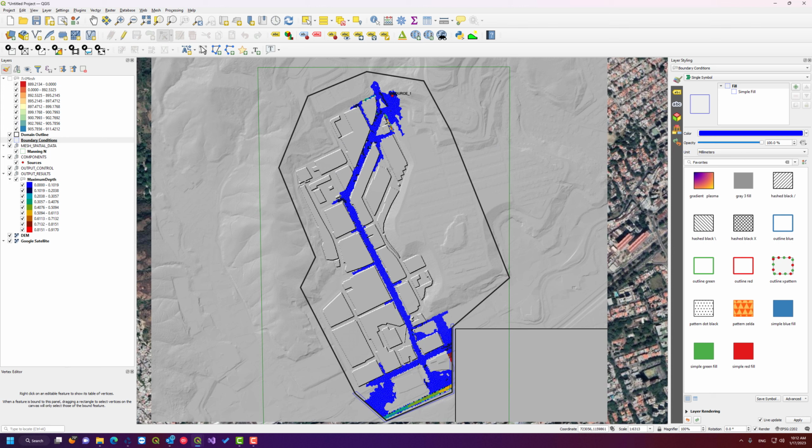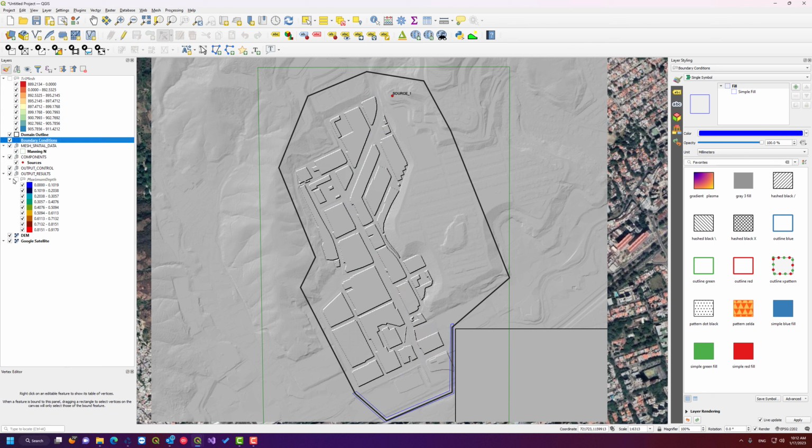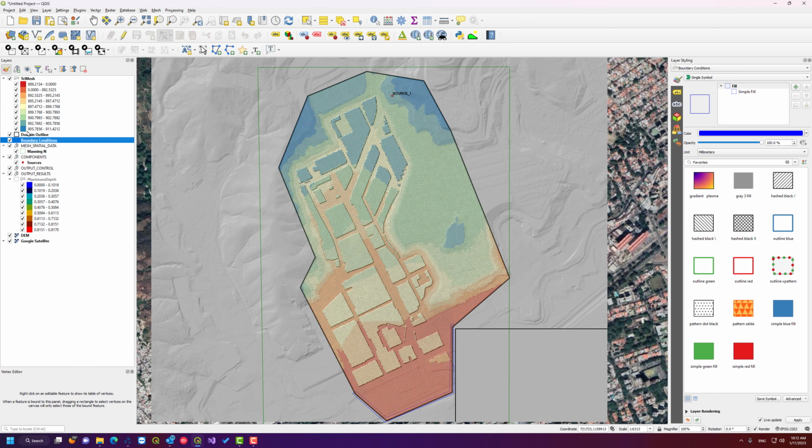So let's go ahead and turn on the heat transfer module. I'm going to go ahead and export the project again. I'm going to disable this output. I'm going to enable my tri-mesh. Since I haven't made any changes to the mesh, I've only changed the domain out, the boundary condition. So this I could just export as is, making sure all of my layers are selected that I need.